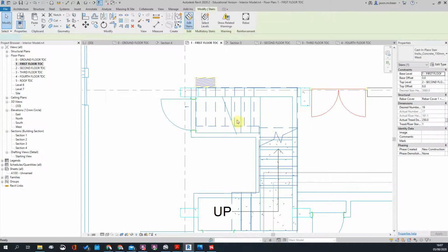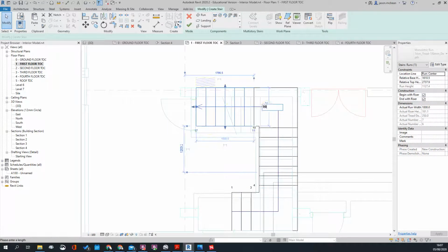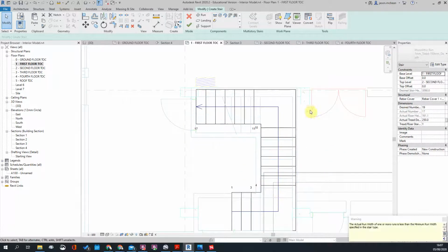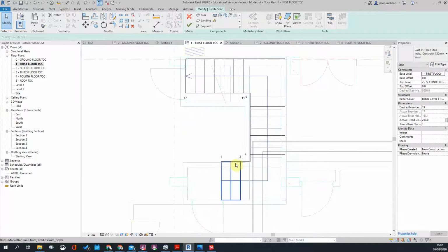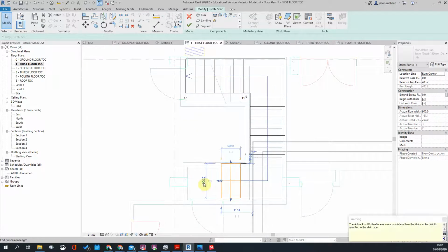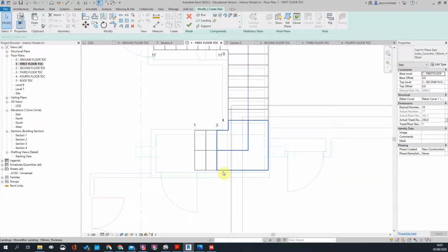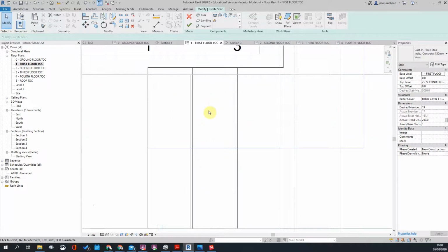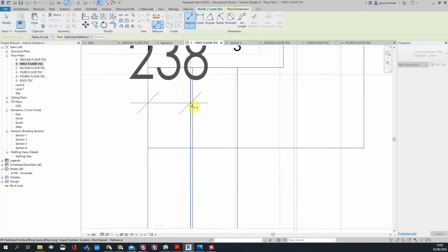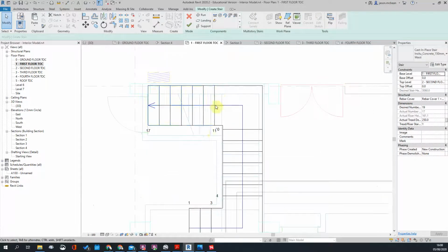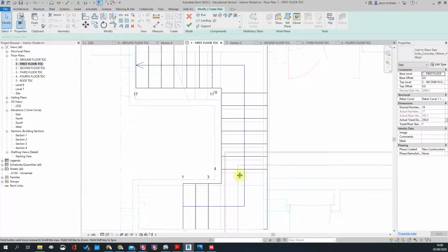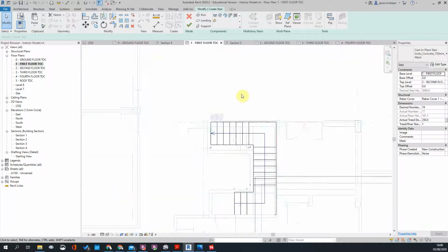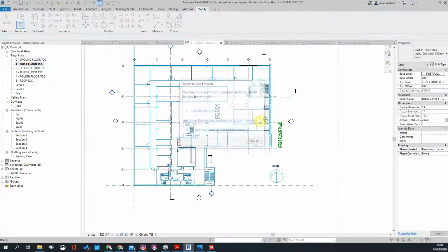So let's go edit stair. 900. Just make sure that your landing should always try and work with the stairs. Okay, so this we can move to here. And not even the risers are the same. How can that not be? That is terrible. Terrible, terrible, terrible. Here you need the right amount of risers to meet that. So I'm actually going to use the staircase as above to make that work a bit better.